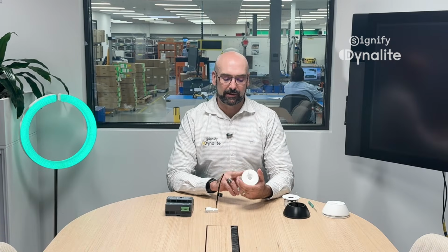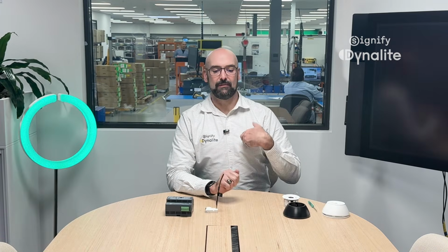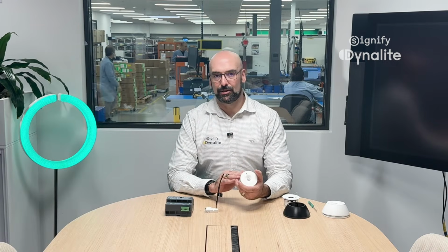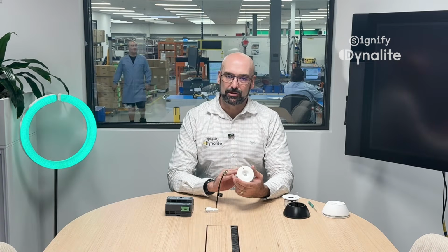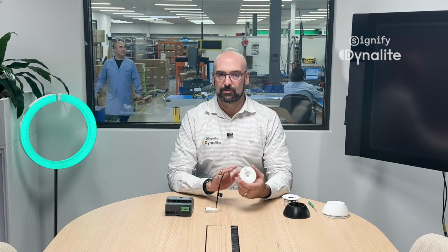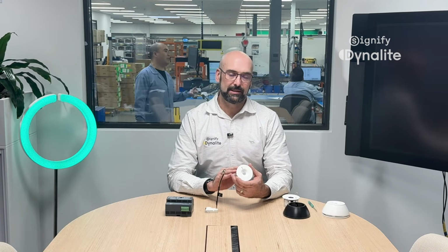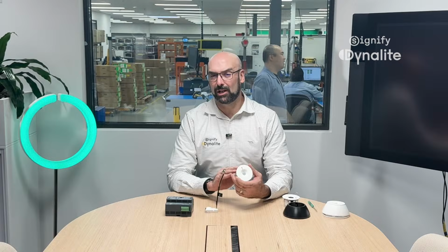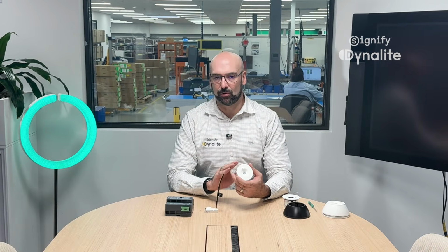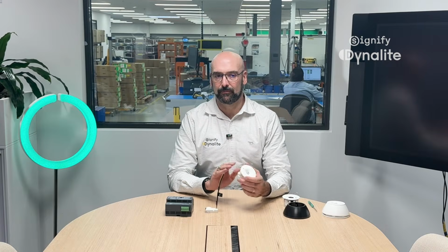So with that low power consumption, this allows us to achieve huge ratios of, say, between 26 sensors and 34 drivers on a single DALI network, getting very close to a 1:2 ratio. This really allows us to deliver a high density of sensors onto a single network, bringing in any design constraints there may be in designing the system for the luminaires and sensor ratios.